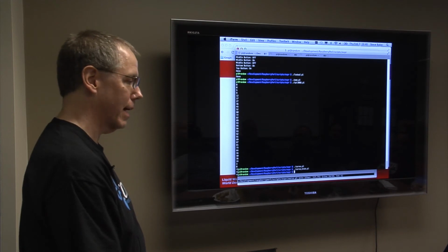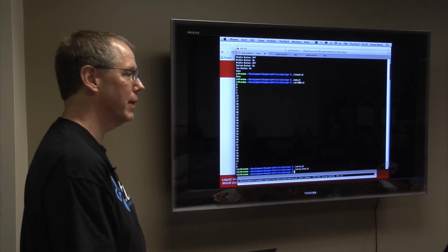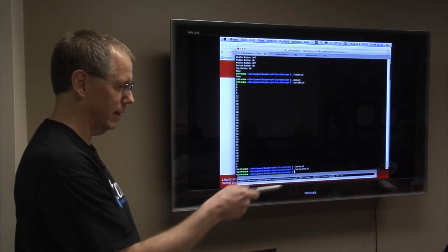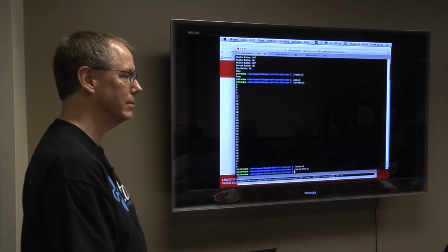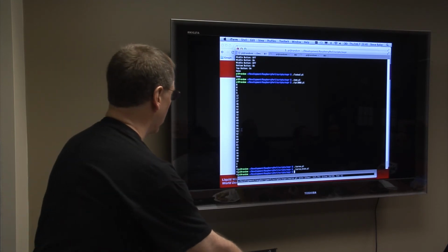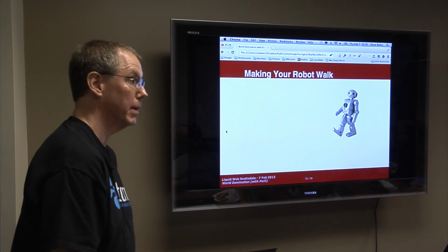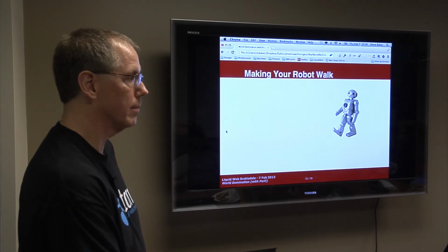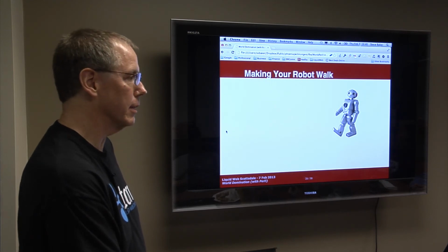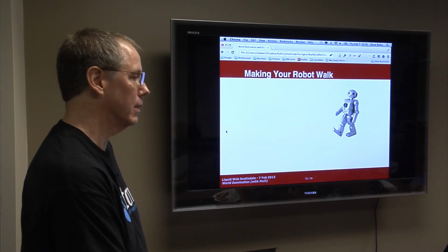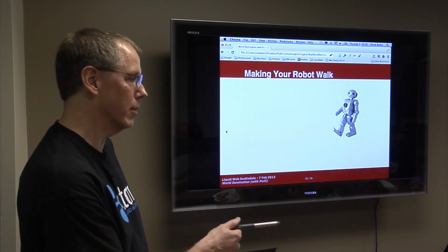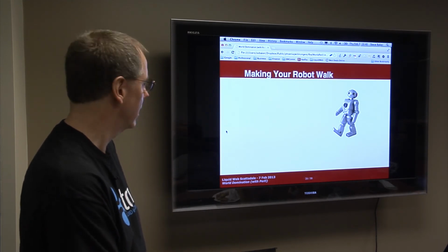I would envision for that kind of thing an Arduino or two out there to handle the important tasks, and then let the Pi be the brain and talk to the Arduino. Cool. And the Arduino could accept it with the GPIO. Pardon me? You could hook it up to the GPIO. Yes, talk to it through the serial ports I pointed out earlier. You can talk to it through that, but the Arduino works in 5 volts. You have to do the level conversion. This is 3.3 volts, but it'd be possible to make that work.